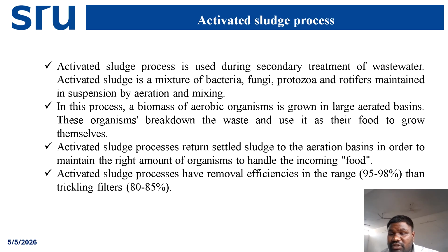In the primary clarifier, the removal of BOD is around 30 to 35 percentage. After the primary clarifier, if we choose the right secondary treatment unit as ASP, then the removal of BOD should be around 95 to 98 percentage.